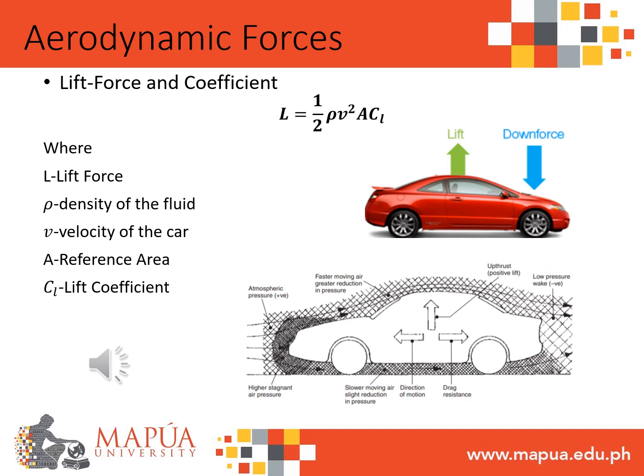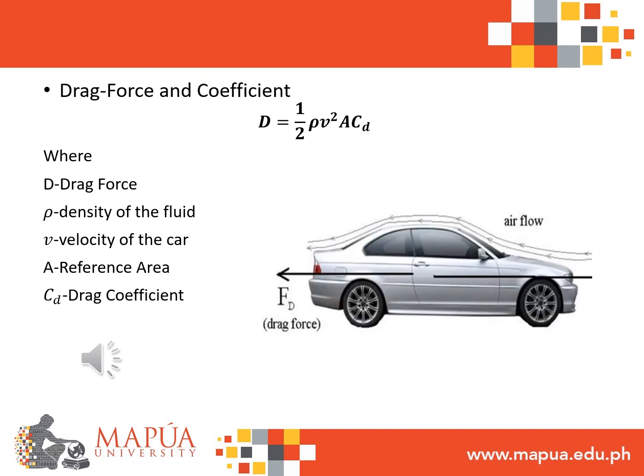In aerodynamics, the lift coefficient is a dimensionless number or parameter that takes shape, inclination, and some flow conditions into consideration. Lift coefficient can also be expressed as the ratio of the lift force to the force created with the dynamic pressure times the area. Moving on, I will now be discussing the drag force and drag force coefficient.